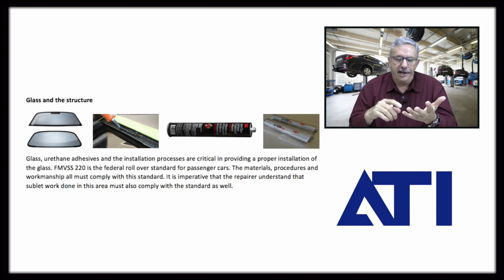The other things that are important here are how we're putting the glass in, who's putting the glass in, and how long the material has cured before the vehicle goes out into the weather, because it says very specifically 24 hours at an ambient temperature of 72 degrees, and it gives a parameter of the temperature. So we may need to look at in the future whether there is stall tie-up time that should be charged into the estimate as well while the urethane cures.